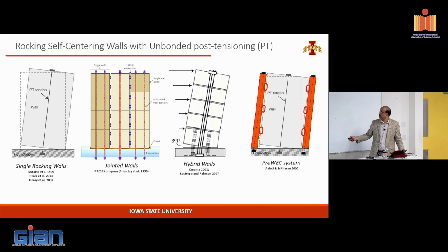Whereas this structure was designed, just so you understand, with a sufficient amount of damping. You design the amount of post-tensioning, so a portion of the forces is going to be taken by this, and a portion is going to be taken by the connector. The combination of the two will be designed to resist the seismic load from a large event, whatever the large event for your region is.